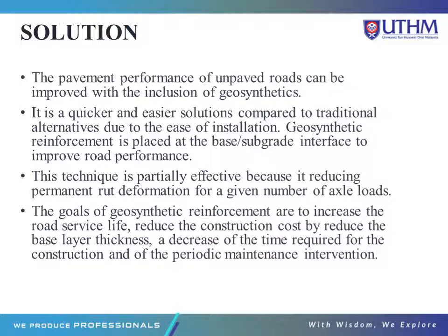For the solution, pavement performance of the unpaved road can be improved with the inclusion of the geosynthetic. It is a quick and easier solution compared to the traditional alternative due to the ease of installation. So geosynthetic reinforcement is placed at the base or the subgrade interface to improve the road performance. This technique is effective because it reduces the permanent rut deformation for a given number of axle loads.